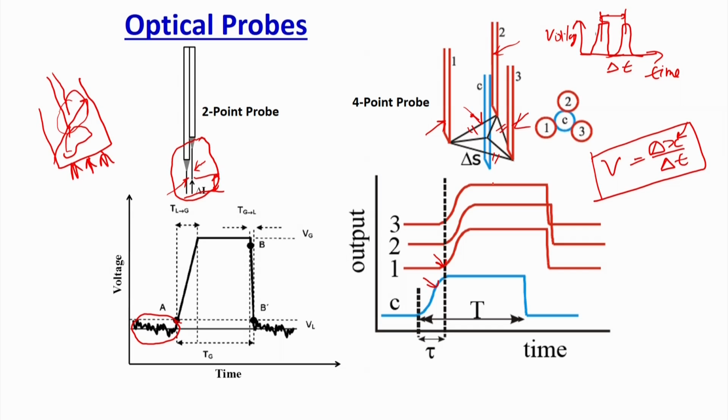Now, once the air comes and touches the first probe, you will record a signal in this way. We will record the time when the bubble has come in contact with the probe, and similarly, once it moves up, depending upon whatever direction it is moving, you will see three different curves of a similar type. If the bubble is moving vertically upward, the time recorded for each probe should ideally be the same.